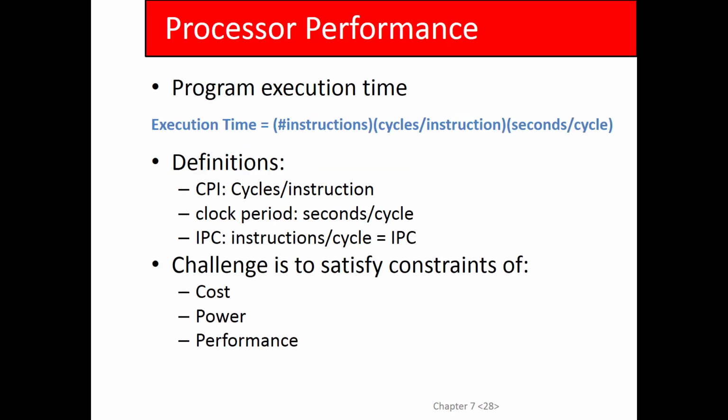Anyway, how do we get this execution time down? Well, we can reduce the number of instructions, and in the old days, that was the main approach. What you ended up with was instructions that did a whole lot of work in one instruction. That also reduced the amount of memory you needed, if you had fewer instructions. Make sense? Although I just contradicted myself, because fewer instructions for memory usage would be the static instruction count, and this is the dynamic instruction count. But you get the idea. If we had a smaller program, even when we ran it, we'd execute fewer instructions.